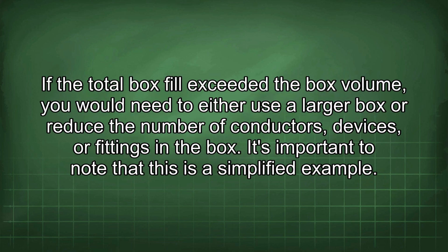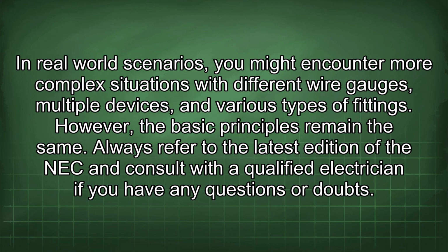If the total box fill exceeded the box volume, you would need to either use a larger box or reduce the number of conductors, devices, or fittings in the box. It's important to note that this is a simplified example. In real-world scenarios, you might encounter more complex situations with different wire gauges, multiple devices, and various types of fittings. However, the basic principles remain the same.